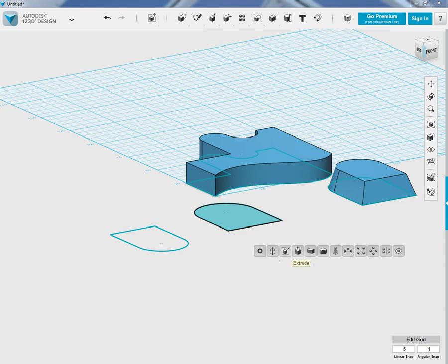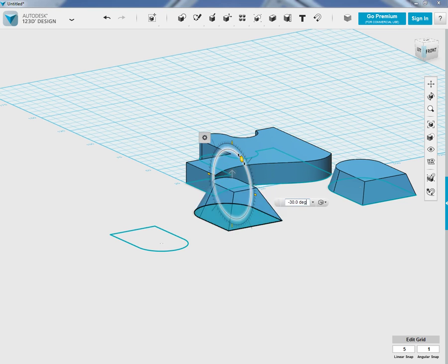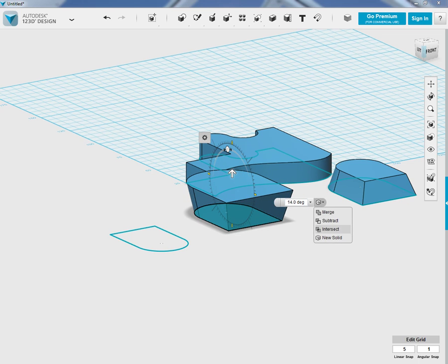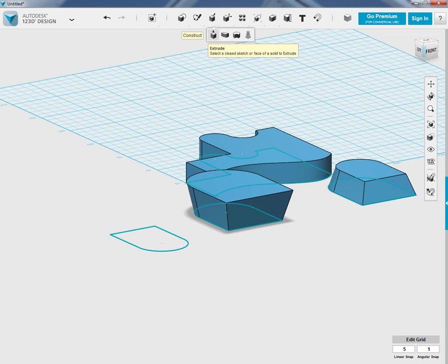In fact, is there an extrude option here? Yes, I can go to the gear here. I can extrude that. There's my little draft angle again. Okay, what's that giving to me? Okay, that's no problem. If I try and extrude this, no, there we are. It's not an enclosed shape. Can't do it. So trying to use some of these 2-point arcs, and it's similar with the 3-point arc, is actually quite difficult to do.